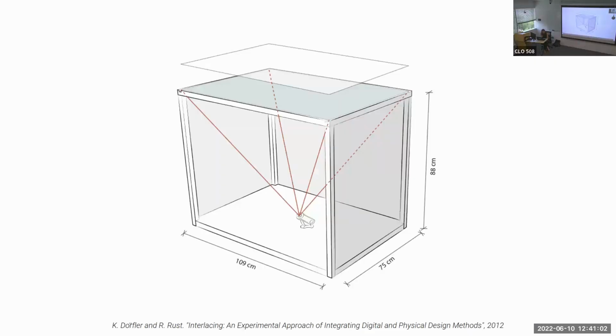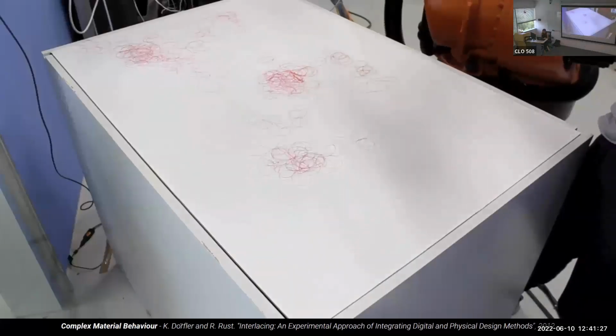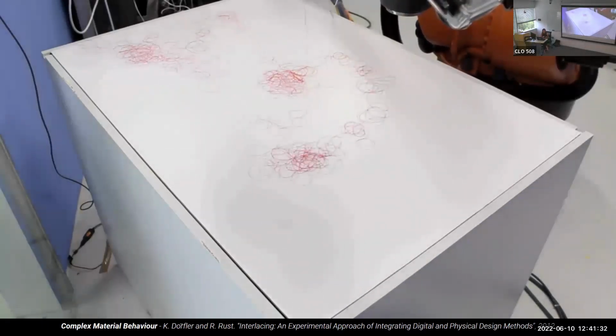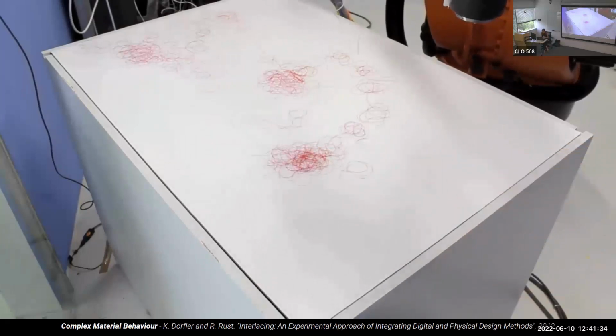So what we tried is actually to embed feedback in the process. With rather limited tech know-how and off-the-shelf systems at hand, we built a custom sensor table that could track elements in 2D. So inside the box, there's a camera mounted monitoring the surface, analyzing the image, and then this information could be used within a fabrication algorithm. We started here to explore fabrication processes using rule-based algorithms in combination with sensor feedback.